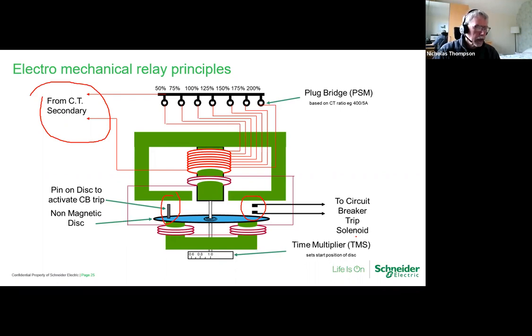That's typical of what you would find in a circuit breaker, springs, very powerful springs. And when a circuit breaker closes or opens, the bang that you hear is the spring energy being dissipated. So the peg, which is conductive, basically, if it short circuits this, is actually going to operate the trip coil. So we need a supply, a DC supply, and somewhere this is now leading to auxiliary power.